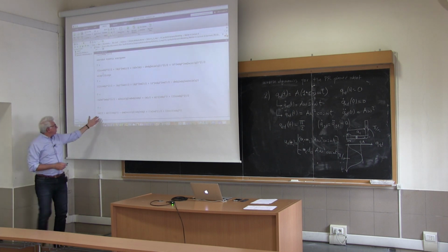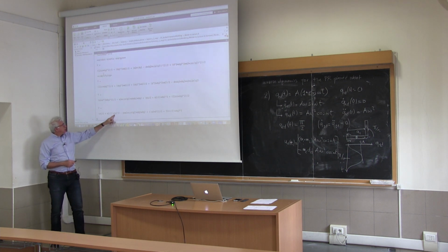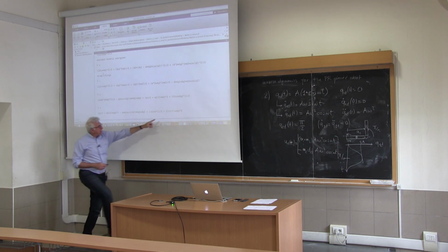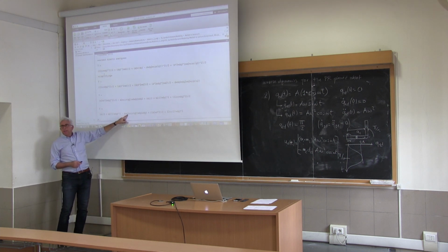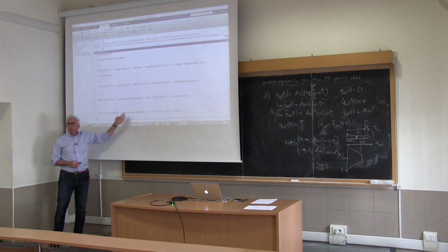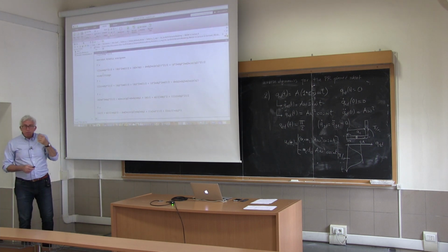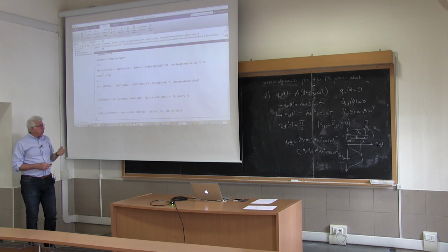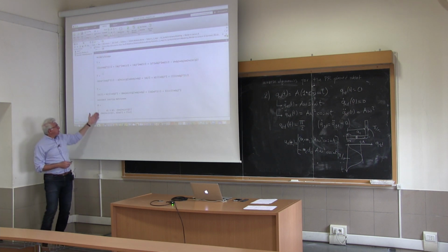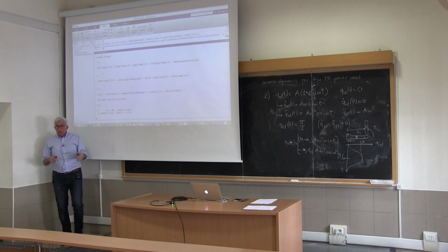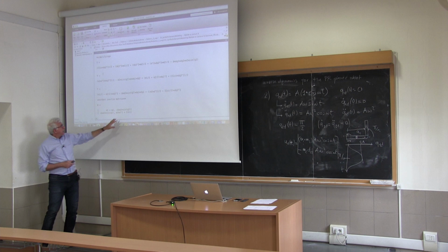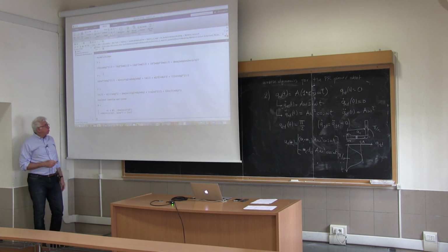So now we have the total kinetic energy: a quadratic term in q1 dot, a quadratic term in q2 dot, and a term in the cross product. From this scalar we extract the elements of the inertia matrix. In fact, the robot inertia matrix is exactly what we found in the slide. So m1 plus m2, and then you have these off-diagonal terms that couple inertially the first joint to the second one, and then a constant term in position 2,2.